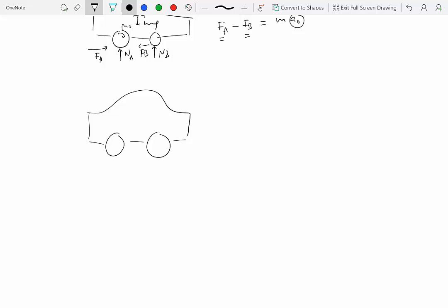Well, you know the rear wheels, even though you're applying a moment on them, are going to slip because there is no friction between the rear wheel and the ground. So that means that the rear wheels are actually going to slip. So if this is the initial position of a line, then after a while it would be this, it would be this, it would be this, but it's basically just rotating while its velocity in this direction is 0, okay? What is happening with the front wheels?